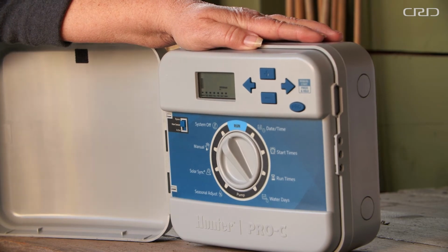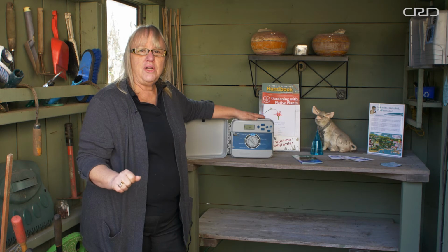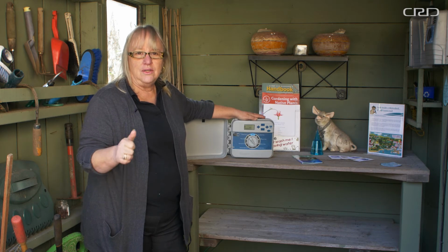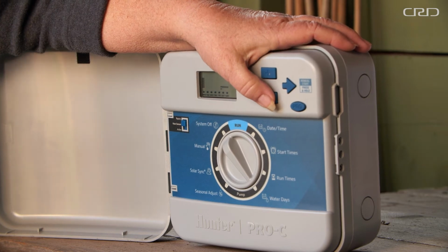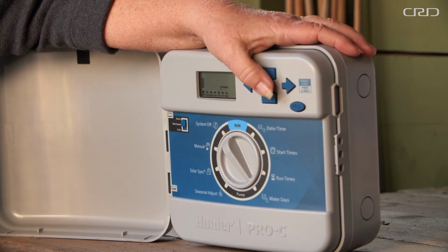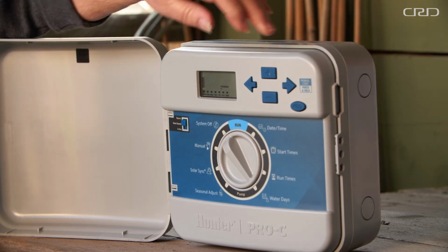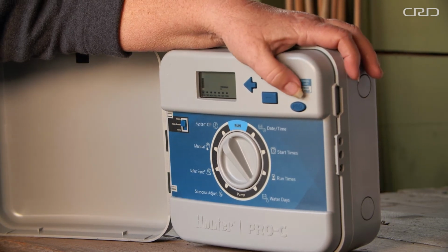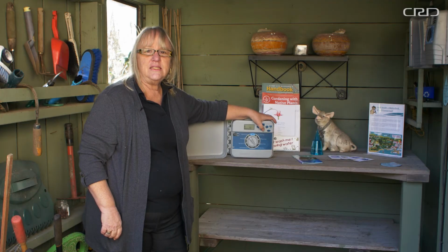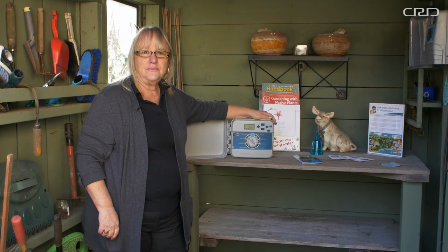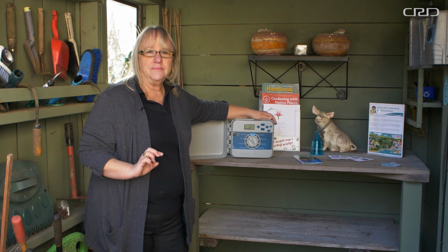Under our watering days, we're going to plus or minus depending on whether I want it to operate. So, do I want it to operate Monday? No. So I minus it off. I will see a symbol that indicates that we're not watering that day. Just by hitting the plus and minus and hitting the forward arrow button, I can change each one of these days to on or off. This is how I set my 2 days per week watering.